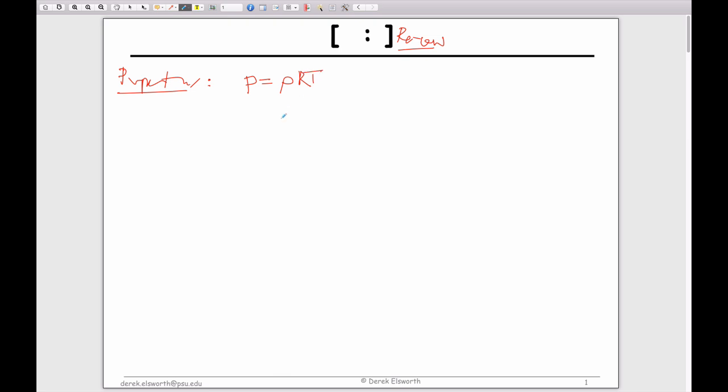What properties do you need? Let me be very careful. This is perhaps good for you. You recognize that, I hope. Ideal gas law. Of course, you all know that. You know that you use absolute temperatures and pressures, and you get densities out of it. You know Newton's law of viscosity. Shear stress is proportional to a constant called viscosity, dynamic viscosity, times a change in velocity in the x direction relative to distance in the y direction. Velocity orthogonal, the change in velocity as you go perpendicular to that velocity.